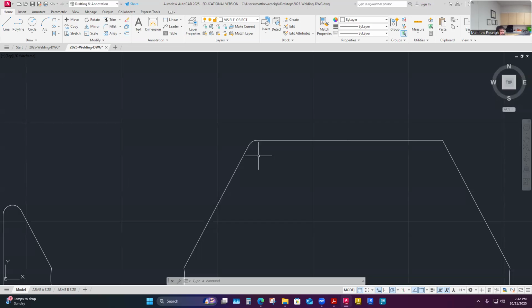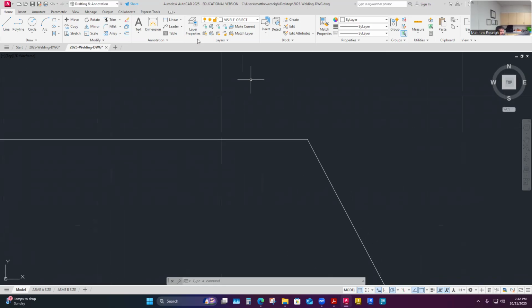Here's the other annoying thing about fillet. It does one at a time. It's faster the second time you've used it, right? So if I go to the second one and want to do that, it's like fillet, okay, or you press enter to go back into it. Now, when you select these and you've actually input a radius, it remembers the last one you did. So that's faster. It's at least got a radius put in, but I've got to remember to set that every time.